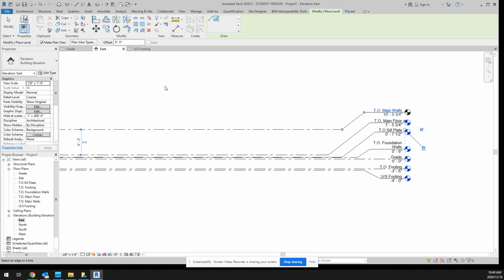And then usually the stone skirt is capped off with a sill to cover it up, to transition from the stone to the siding or whatever you're putting above the stone. So then you'd create a top of stone sill level. Stone sills are usually 2 inches thick. Okay? So depending on how creative and complex you want to get with your design, you may have to establish additional levels in order for you to draw everything you need to draw.